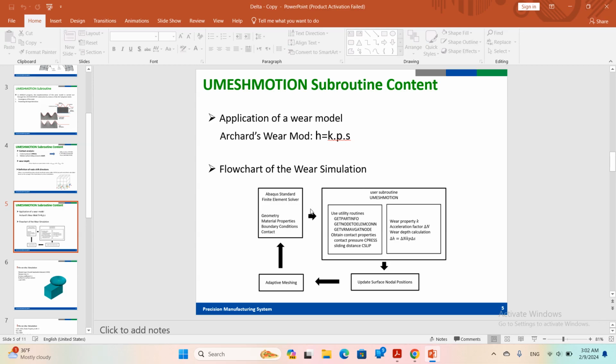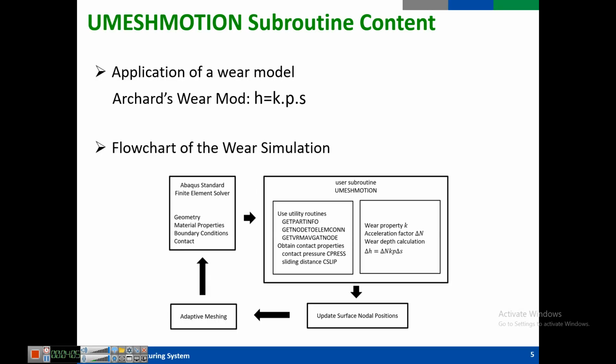I also explained this flowchart in my previous video. For performing a wear simulation using the Archard model, you need to define wear coefficient, CPRESS, and your sliding distance. This flowchart illustrates the wear simulation process using UMESHMOTION subroutine.